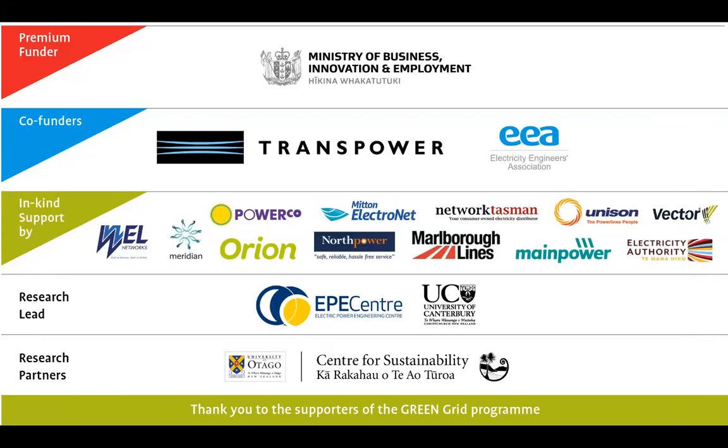So have you considered if customers have more than one EV per customer? Yeah. So I guess that comes back. Sorry, the question was, have I thought about penetration levels? Well, actually, this is essentially, have I thought about EV owners that might have more than one EV? There's two ways that you can think about that, because the EV penetration level is the number of EVs divided by the number of connection points, and your 100% penetration level could actually be that only 80% of those connections have EVs. It just so happens that some of those do have more than one. So it's about how you interpret that penetration level that was previously discussed.